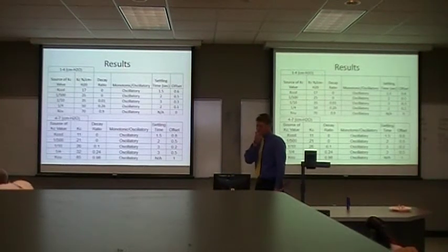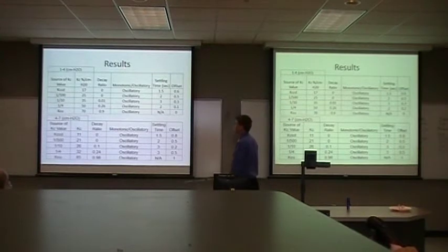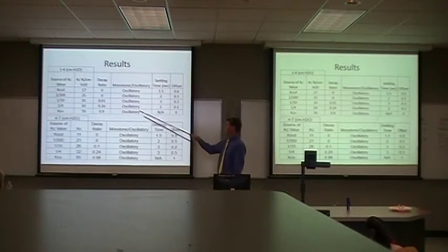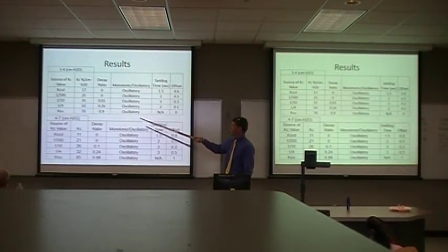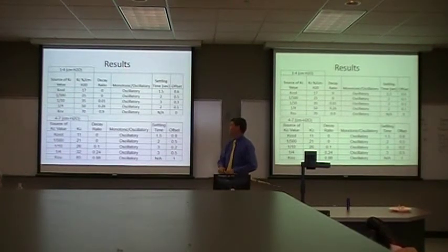Okay. This was for the proportional controller. We had the different KC values, I believe this is the experiment. So these are the actual KC values we found for each decay. The first one being critical decay, and for pressure from 1 to 4 centimeters H2O, Brad found that the KC for critical decay was 17, for 1/500th decay, 25, 1/10, 35, 1/40, 50, and for ultimate decay 70.